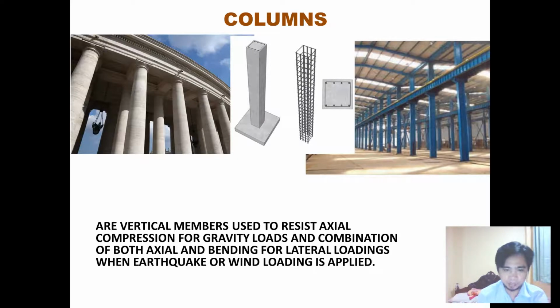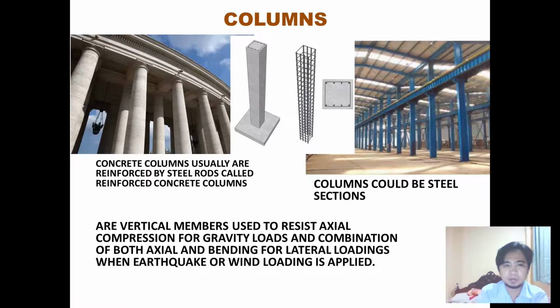Used to resist axial compression for gravity loads and a combination of both axial and bending for lateral loadings when earthquake or wind loading is applied. It could be in the form of reinforced concrete or steel section.